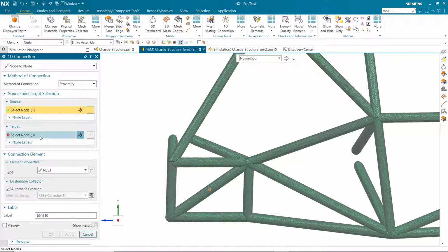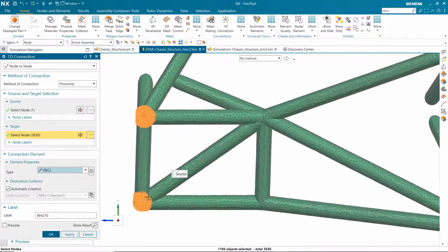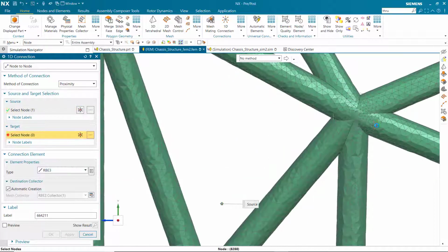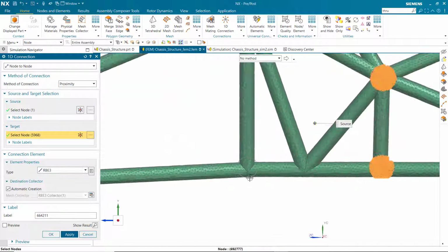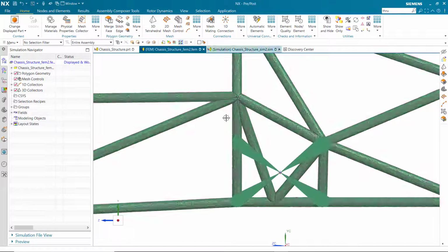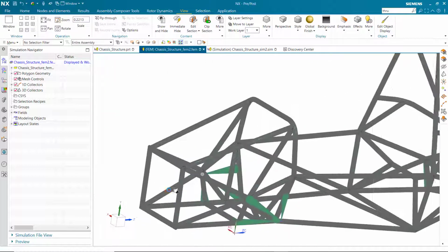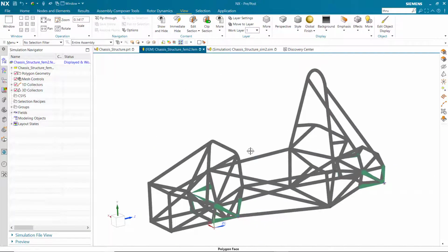A way I could slightly improve the fidelity would be to use the split face command so that I'm applying these constraints and loads on the outward faces of these and not grabbing the internal faces of these beams. For a first pass of this kind of simulation on this model, however, this is perfect, and with that, we're actually finished and ready to move on to the simulation.